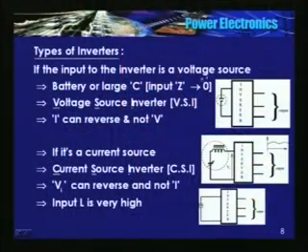So even in a VSI, voltage source inverter, current does reverse. Voltage polarities cannot reverse here. I have shown here 3 lines indicating a 3-phase inverter. You can have a single phase inverter also.